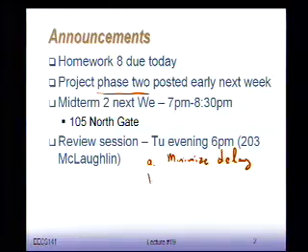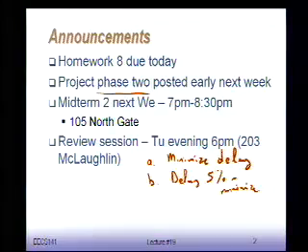That's 1. Number 2 is suppose you can increase the delay. So from the first phase, we'll tell you what the normal maximum worst case delays would be, right? You figure that out. So you know what the worst case delay over your first topology. Suppose I can increase the delay with 5%. Minimize power. I give you some slack in the overall design, and use that slack as well as topology improvements to minimize power.